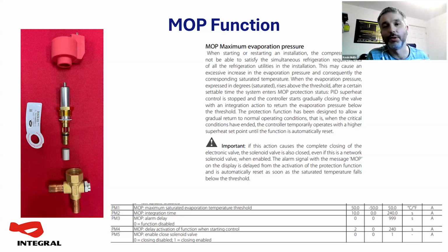Let's say if you want to control load on HT, you can set that to limit the opening at like -1, -2 C evaporating. But if you're operating something like floating suction, that can become an issue, because you can inadvertently float suction up to a point where you've hit the MOP setting in the valve. Same with Danfoss, and the valves will all start locking up, and you'll be like, why have all my cases stopped working? The evaporating temperature is still cold enough for them to work.